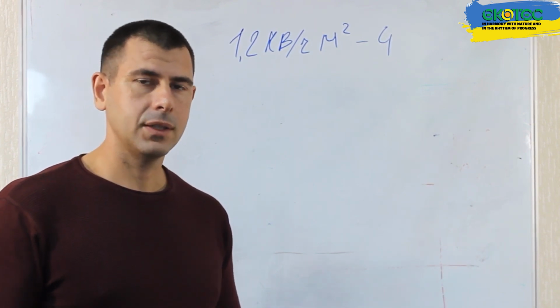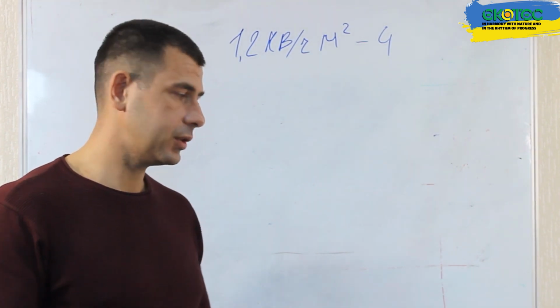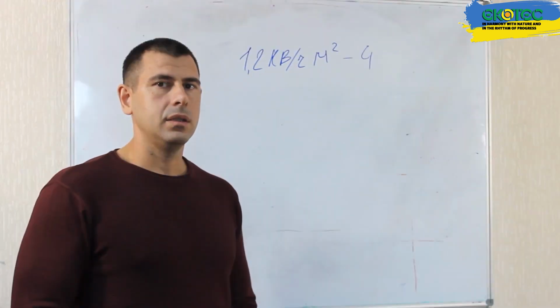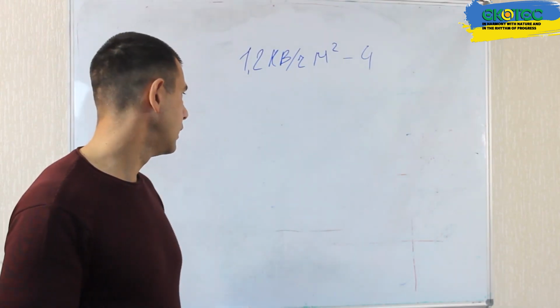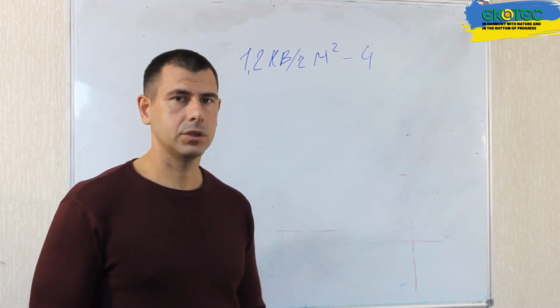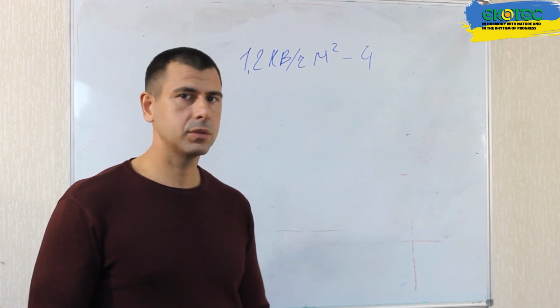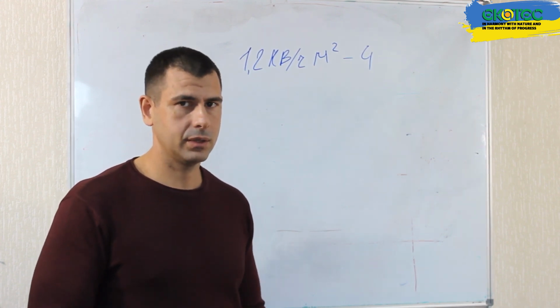The last point is energy consumption. How much energy do we need for this system to operate? We have 4 fans that consume about 0.8 kilowatts per hour, meaning they will operate for 20 hours a day. There are periods when they may not operate because the automation system is designed to turn off when the ground surface temperature and air temperature reach 25 degrees Celsius.